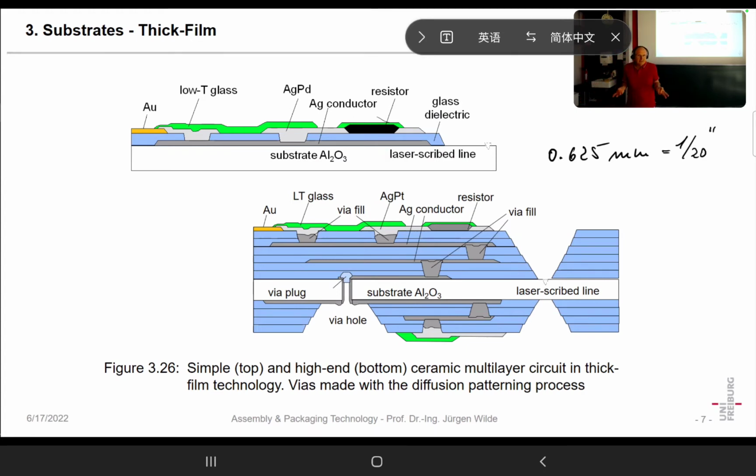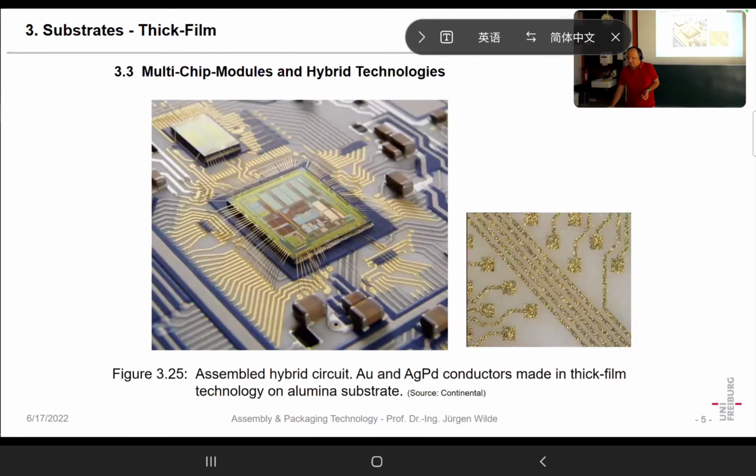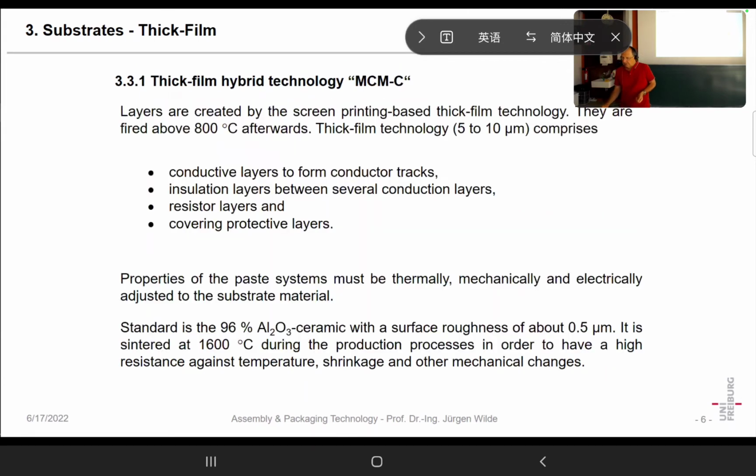And there are two strategies to overcome this. One strategy is having a higher wiring density, so you need less wire, less layers, just more conductors on one layer. And the second is just use another technology. Also, that's a reason why people in some applications go towards high performance printed wiring boards.